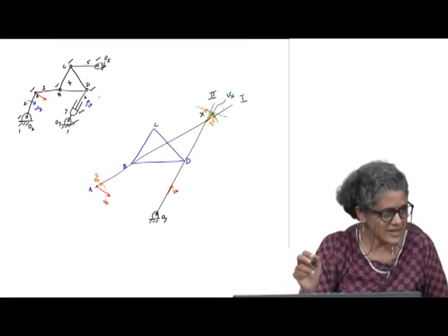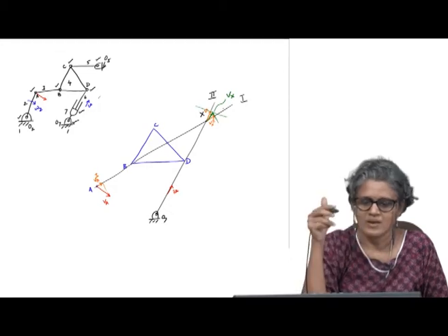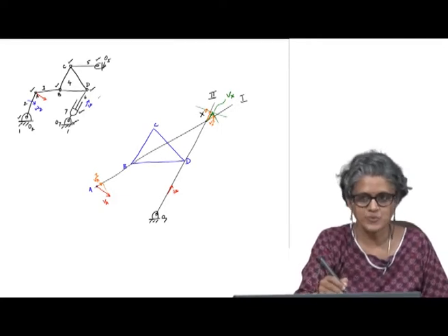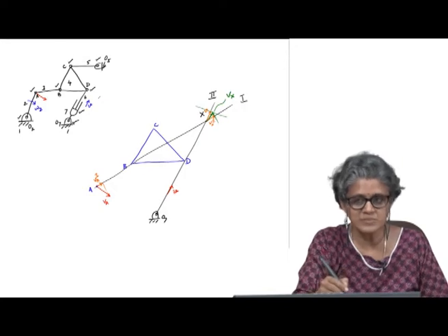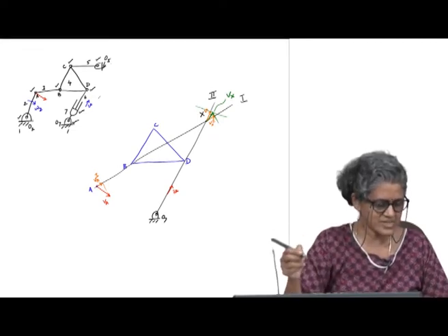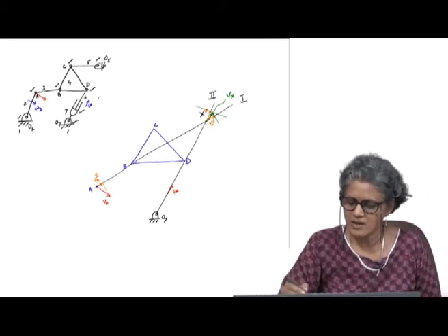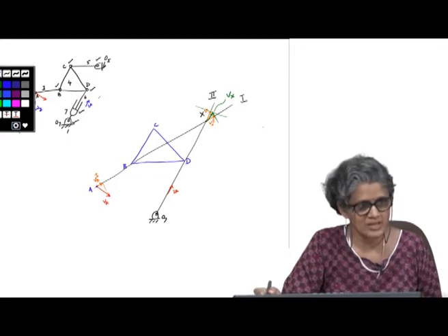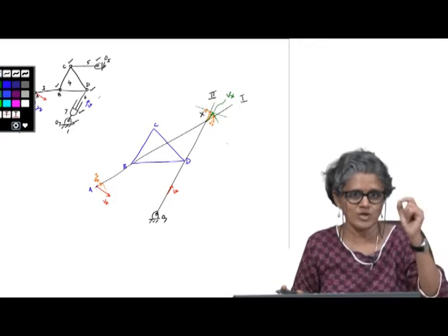So, this method relies on how the motion is transferred through the motion transfer points. With this, there is one more motion transfer point through which I can draw the third auxiliary line, and I do know something about how the motion is transferred through this point C, because of CO5. So I can draw the third auxiliary line through C and X, because now I know the velocity of X is also on this coupler. I know another component also for the velocity of C.